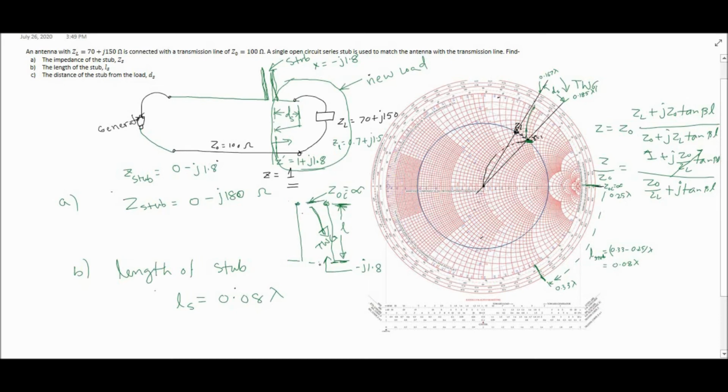Per stub, this is the load, and this is the characteristic impedance. So this is the stub characteristic impedance, and this is the load of the stub. The load is open circuit here. If you say ZL is open circuit, that's infinity. So this gives back to 0, and you'll get normalized Z equal to negative j cotangent beta L.